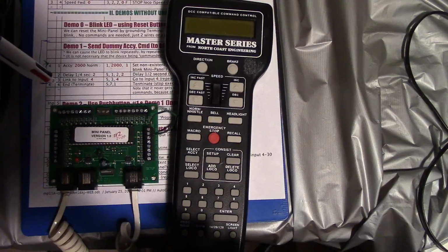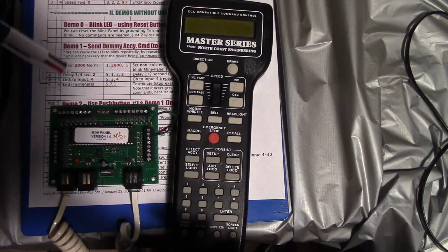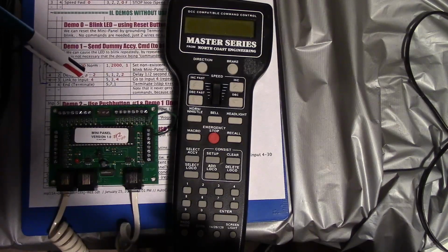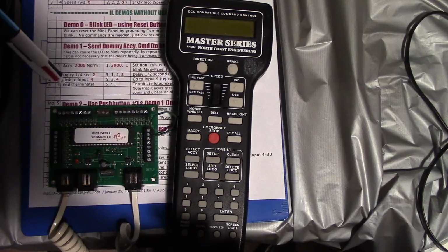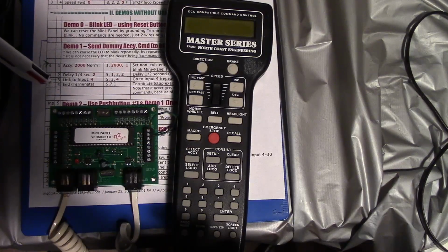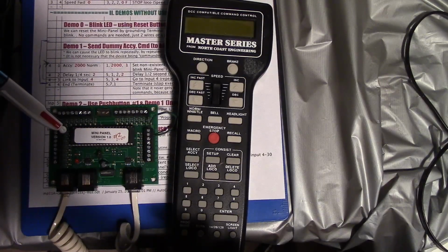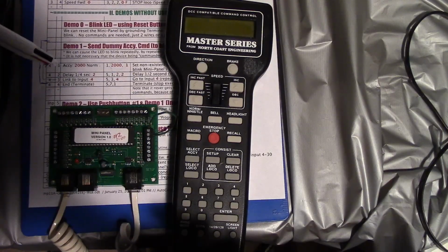The second statement is a delay, a quarter second times 2. That's half a second, which just gives half a second between blinks. Then the third statement says link to input 4, and that takes it up to the top again. We're using input 4 for this. We haven't talked about setting up the configuration of this Mini-Panel, but as it comes defaulted, the memory is set, the cab address is 3, and all this memory is available. We'll talk about the configuration later, but this will work for what we're doing.